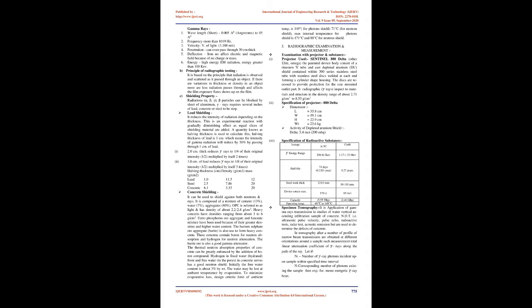The chemical properties of all high-density aggregates should be evaluated before use in high alkaline environments as found in cement pastes, and for long-term durability such as alkali aggregate resistivity, sulfate and chloride attack, and other impurities. The cost of HDC increases with density but not necessarily in direct proportion. Aggregates should be selected for their shape, free of flat or elongated, maximum density, workability, and cost. The grading of the coarse aggregate should be uniformly graded between 10 mm and 20 mm as grade 1 and 4.75 mm and 10 mm as grade 2.